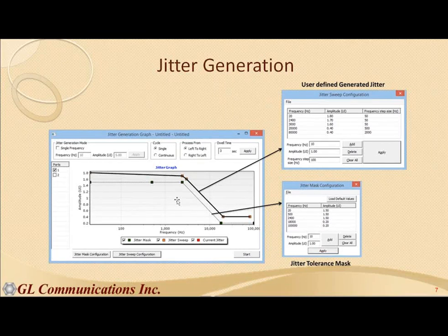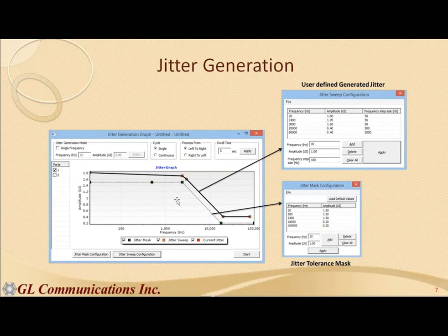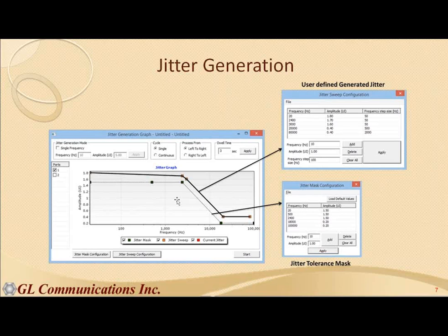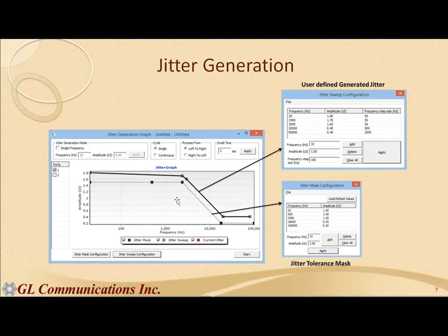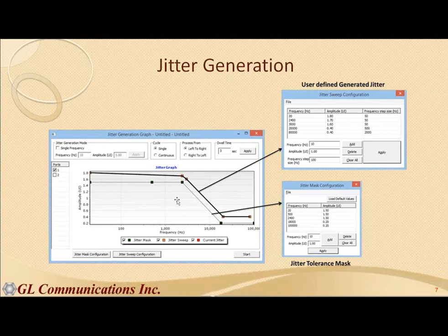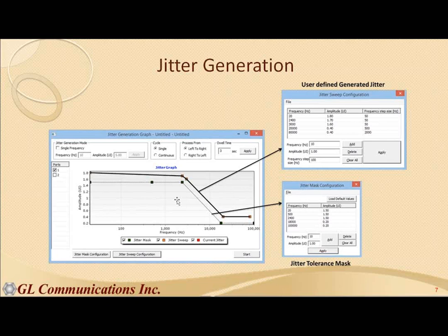In other words, is it changing rapidly, that ideal versus instantaneous, or is it changing very slowly? Obviously, slower is better, right? Because if jitter is high frequency, then the receiver is going to have a problem getting that bit. So just to make it somewhat simple, jitter can be measured in the time domain as just the displacement between ideal versus instantaneous, or it can be measured in the frequency domain as to how it is varying over time.